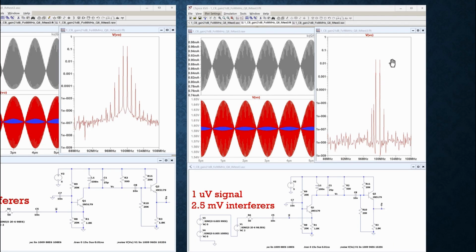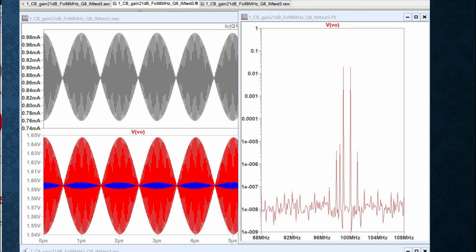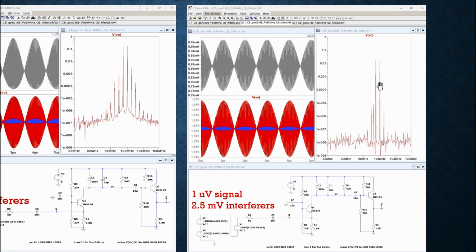When we do that, they are lower in level at the output than they were before. That's no surprise. We dropped them by 20 dB, a factor of 10. So they dropped from, what is this, 0.1 volt, about 0.2 volts down to 0.02 volts. Okay, that's expected. Exactly right. The intermod products, the 3rd order intermod products that flank them are here and here.